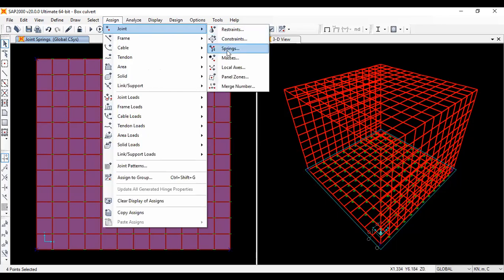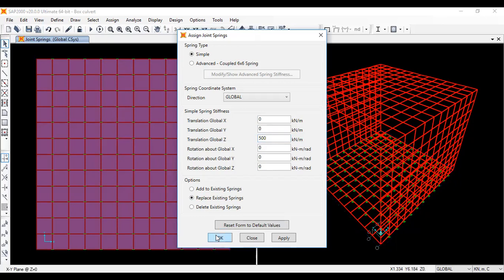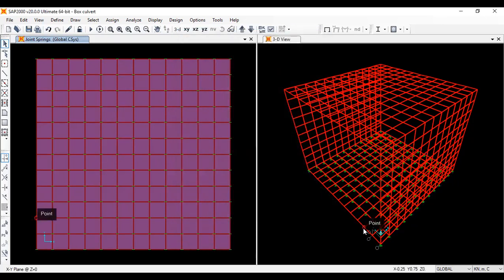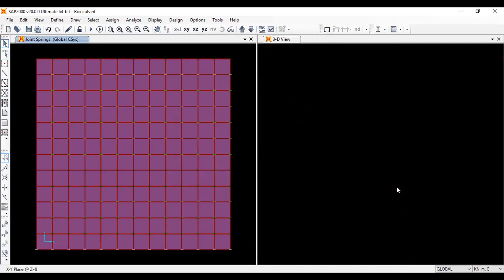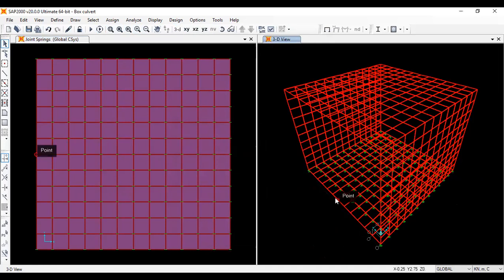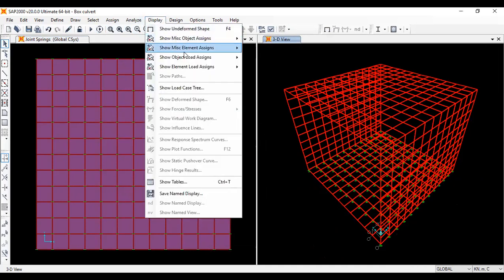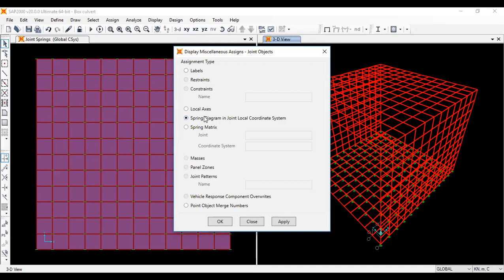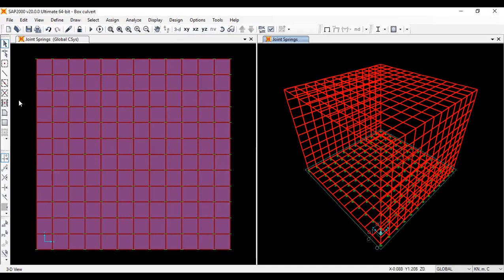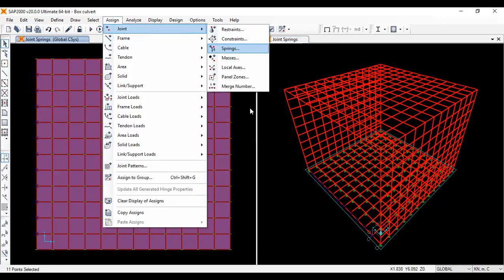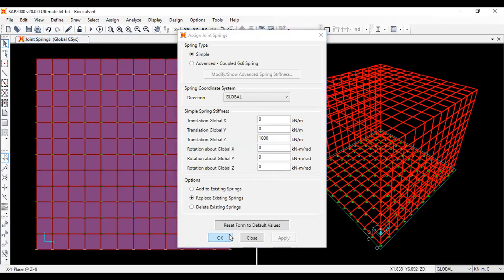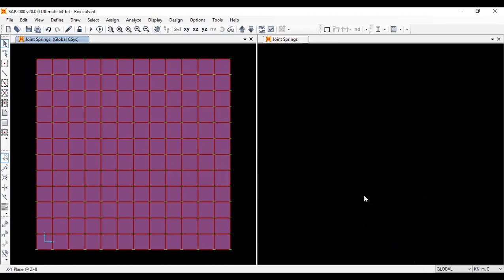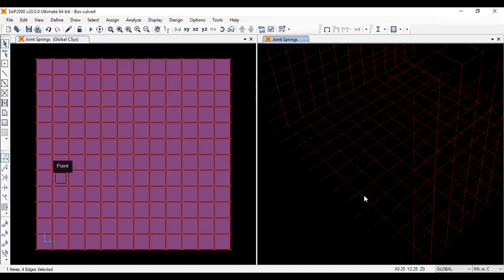Assign springs 500. That's done. I think I have not. Is it? Oh, I haven't, I think. Check elements. Yes, I haven't. Select these joints, right. Springs 1000. Okay. Now it's okay, I think. Yes. You can see the spring is there,